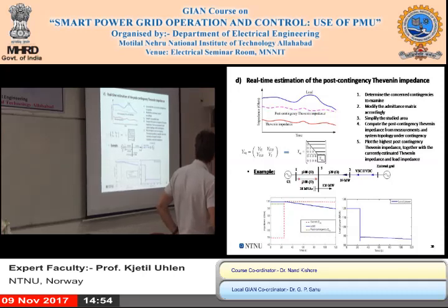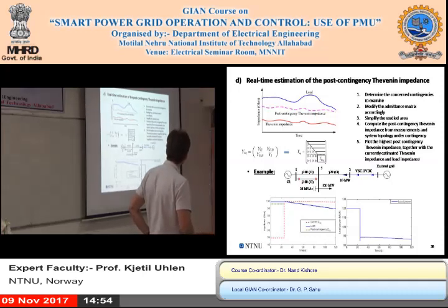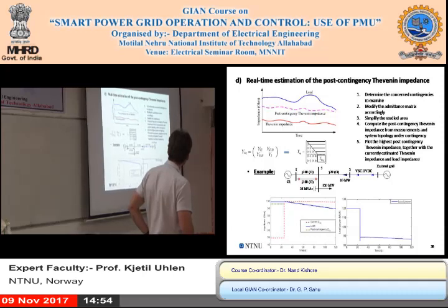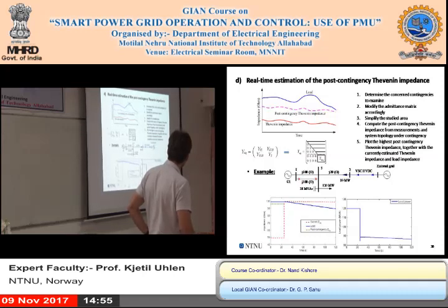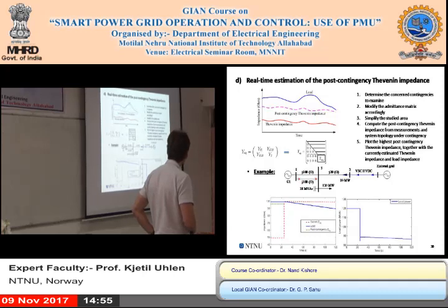Then the impedance is 50 ohms. But you know that if you lose this line, your impedance will be up to 100 ohms. So you could plot that, and then you would know that in this case, with this load impedance, you're already in near trouble. So this is just a simulation of what happens if you lose this line. Then the voltage drops and also the power drops. So you're saved exactly, but the margin is very small.